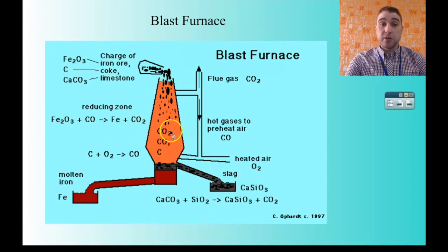The iron produced trickles down the sides of the blast furnace and collects down the bottom. You get a layer of slag being produced. That's your silicates, that are your waste products. And you tap off the iron down the bottom here. So again, keeping this blast furnace nice and hot, that's where the energy cost is in this process.